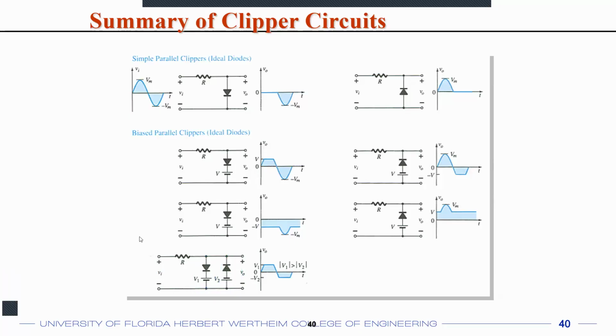You may have heard something about the ESD protection circuitry for any electronic circuit. ESD stands for electrostatic discharge, and electrostatic discharge can happen from anywhere. For example, my body can store voltages up to thousands of volts. And you can see in any ESD protection circuit document that they are going to protect the circuit up to, let's say, 3000 volts or so. That is because if I accidentally touch that electronic component, I can damage it because my body has a very high amount of charge or very high voltage.